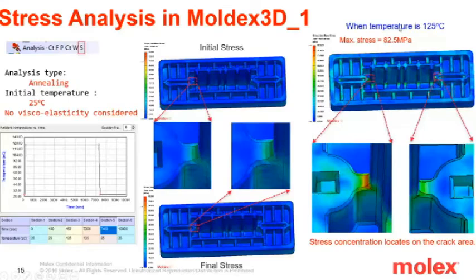But when I check the stress at the temperature of 125 degrees C, I also see an obvious change in this crack area. See this difference? So it's also a good indicator that this will be a problem for us.